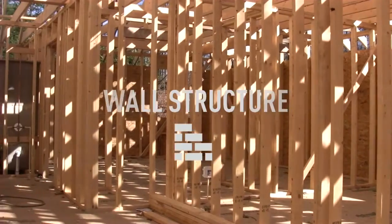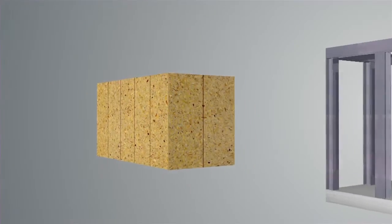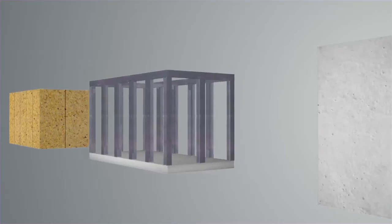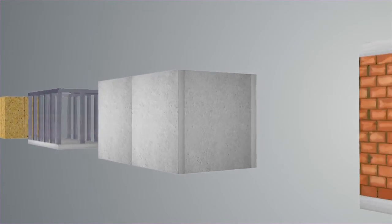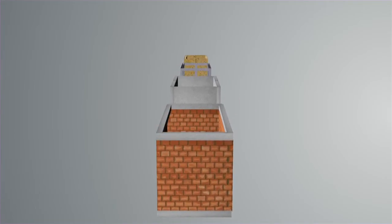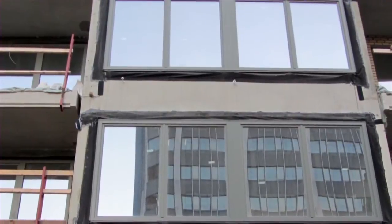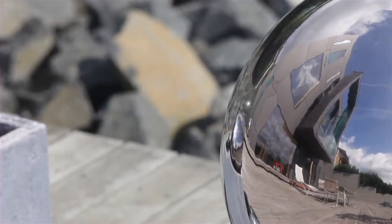Wall structure. The main structural wall can be a timber or metal lightweight frame, or a massive masonry construction, such as concrete or brick. This structural wall needs to carry the weight of the facade and resist the power of the wind. It should also be airtight, especially around openings such as windows. Airtightness prevents moisture ingress and ensures that the building remains thermally efficient.